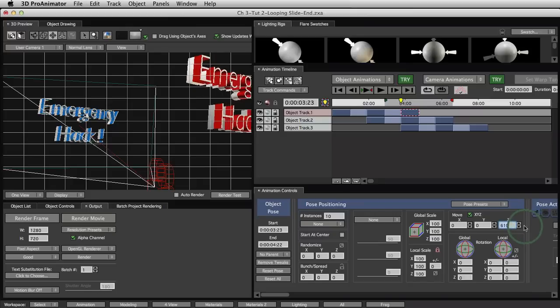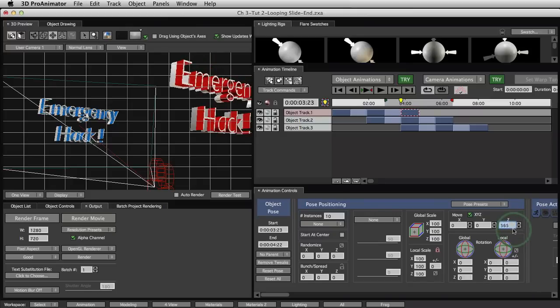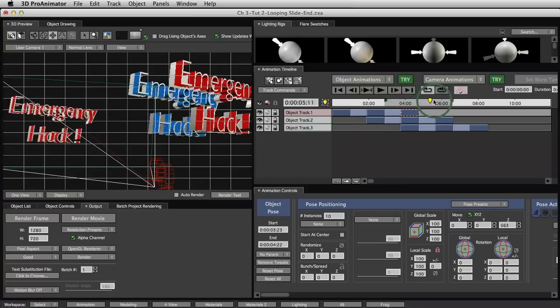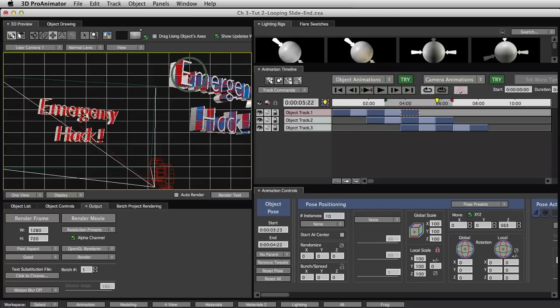So where was that? About right there, right? Yeah, nice. So that was 1, 2, 3 down and 1, 2, 3, 4 over. We can double check that position by moving the next one over and seeing if it lines up. Oh, see, that's perfect. When you end up seeing these sort of zigzag lines where it goes blue and red and blue and red, that means the planes of the objects are in exactly the same space. So the rendering engine can't figure out whether to show the blue one or show the red one, so it just alternates, and you end up with this.